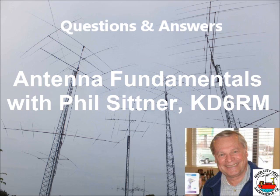Remember we talked about the dipole antenna? In a dipole antenna you've got the two halves. Well, in a ground plane antenna, the vertical element is a quarter wavelength, and the ground plane, these 3 or 4 spokes, constitute the other quarter wave. A quarter and a quarter make a half. It looks this way in a dipole. In a ground plane, it looks this way. And there are also vertical dipoles. There's no reason you can't have a vertical dipole. They work quite well, actually.